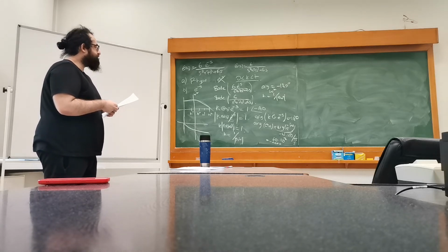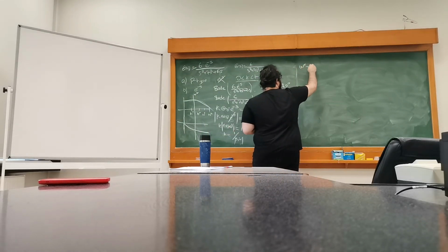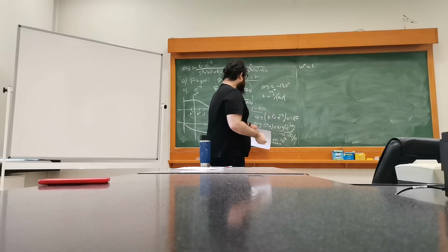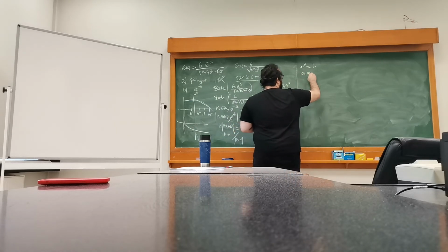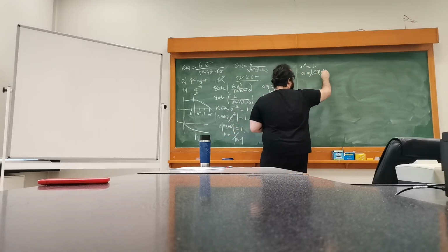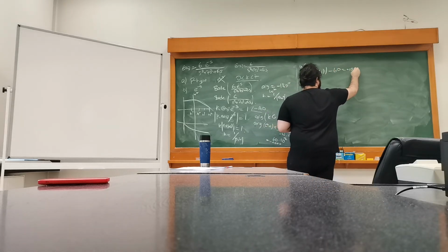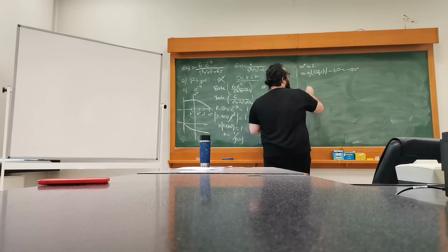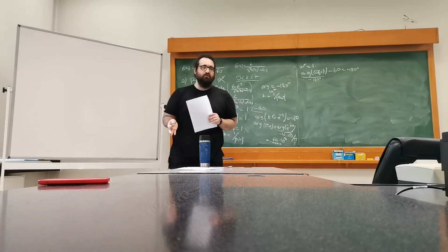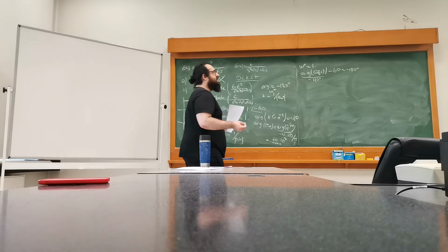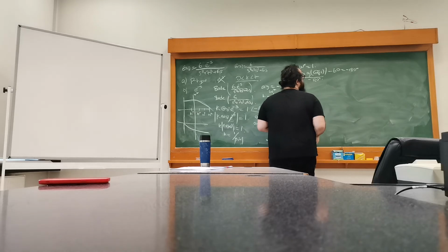So yeah, you can start with a guess. For example, if you guess that omega is equal to 1, just roughly guessing, then we should look up what the argument of this is. So the argument of j omega here minus, let's say 60 degrees, should be minus 180 degrees. If this is roughly 120 degrees, then I'm at the correct point because it satisfies the equation. If it's low, I might have to increase omega because it still didn't hit 180 degrees.